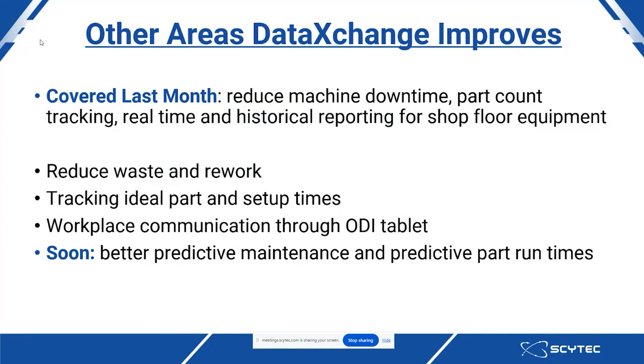Now, some of the other areas that DataXchange can help your shop floor out with is reducing waste and rework. You can also do some tracking of ideal part and setup times, where you can take an Excel document and have that uploaded into DataXchange for what you were looking for, ideally, in terms of how you should be setting things up on a machine, and then compare that to what is actually reported to make sure that you get the most accurate OEE information available.